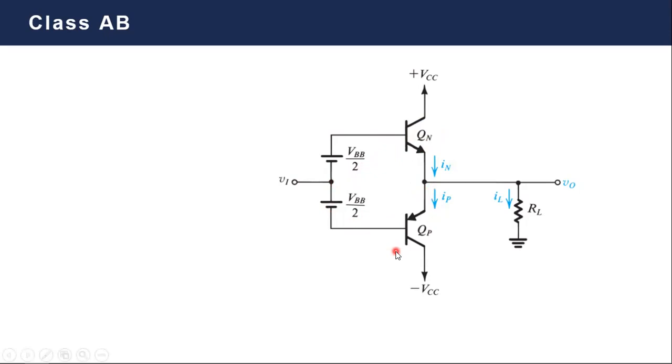So instead of having two transistors off in the center of the dead band at zero input voltage, now your two transistors will be turned on, as you can see. And this is a very efficient way of overcoming the dead band. In order to turn this into equations, we will simply deal with this as a p-n junction. Here we have the base-emitter junction, and here we have an emitter-base junction, because this is an NPN transistor, and this is a PNP transistor.